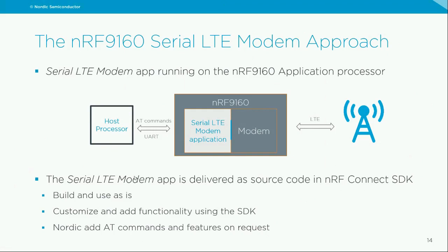You can basically build it and use it as is with the current feature set that we have for basically connecting LTE, configuring the modem and the network. We have support for CoAP, MQTT, FTP, basically TCP, UDP communication, and so on. Or you can also customize and add other functionality using this SDK. You can add dedicated libraries that are needed for certain device management in certain carriers. You can add FOTA support. You can add your own middleware and your own stacks and still have them as part of the application.